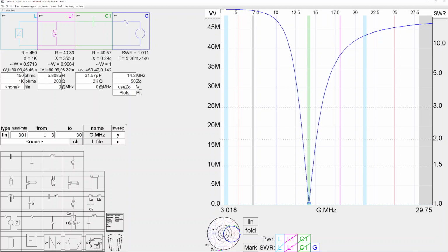And generally, for the same LC values, a solution will have smaller bandwidth for lower frequency bands; the Ls and Cs typically go up and the bandwidth goes down. And conversely, if you go up in frequency, I can use smaller LC circuit components and the bandwidth goes up and wider. Okay, so that's a lot of fun.